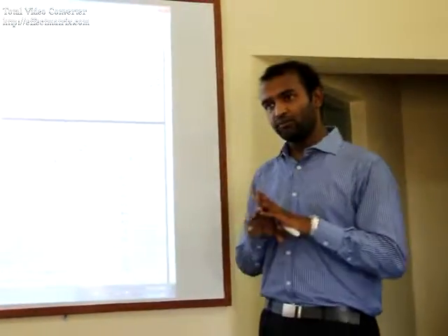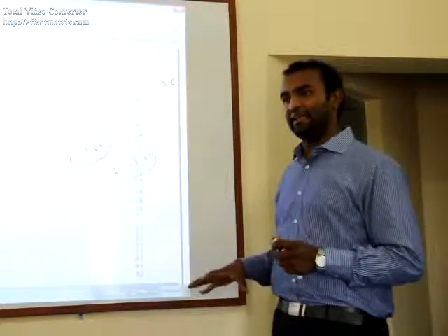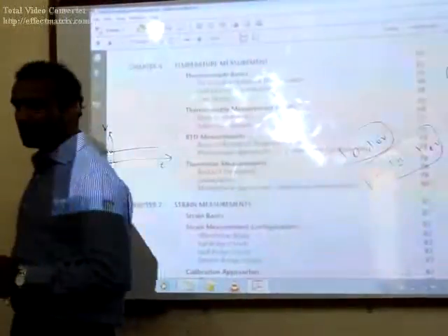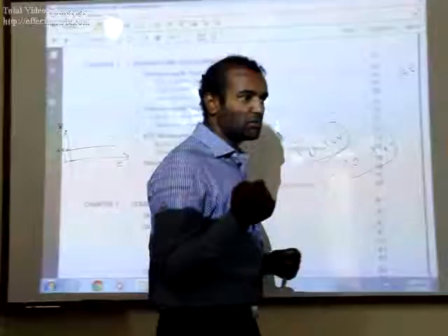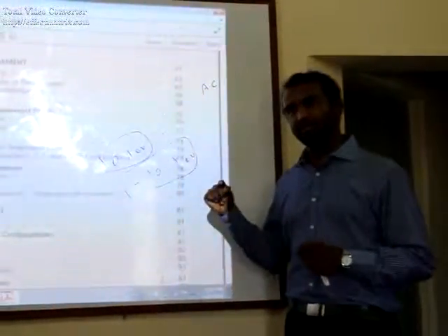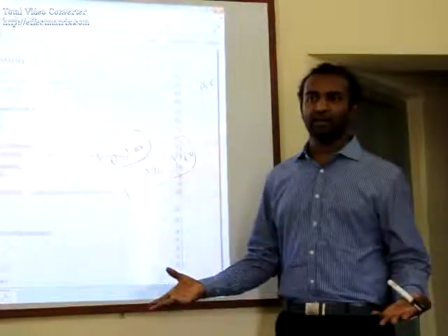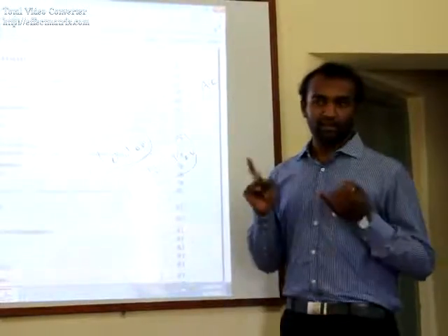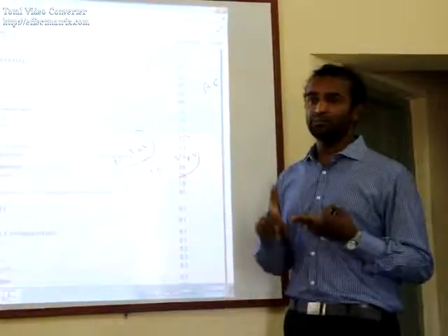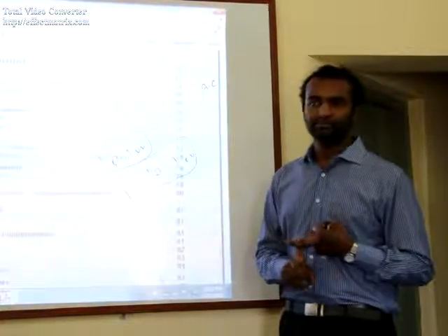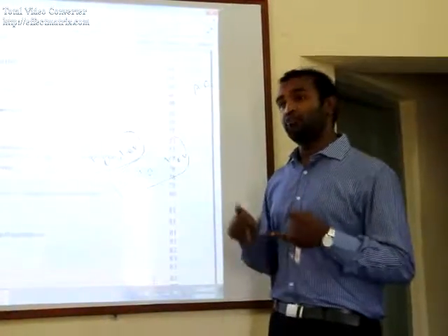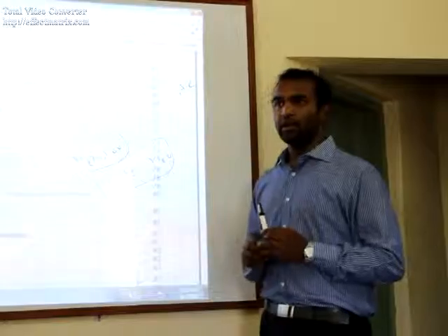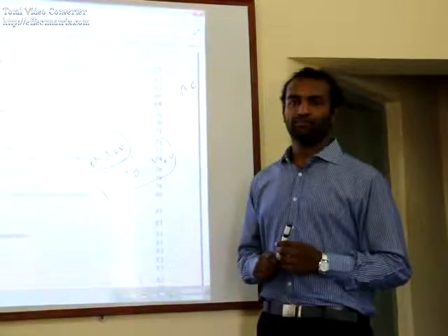From here onwards, there will be detailed technical specifications like what exactly is an RTD, what exactly is a thermocouple, what exactly is a temperature sensor. How are they going to differ with respect to parameters? How are they sending their signals? I said you have a resistive form, and a capacitive form. The various temperature sensors which are available. Now we should be in a position to tell why I should use a thermocouple for a given application, and why I should use an RTD for a given application.